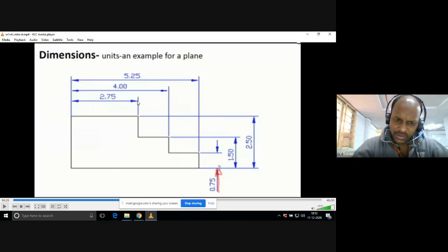Okay, you have to draw like this, just a bubble inside it, and you have to place this dimension line in between extension lines. One vertical line I am showing you here, and other vertical line I am showing you here. You need to keep the dimension line within these extension lines. These are known as extension lines. All are drawn with 2H pencil only, except the main drawing, which is drawn with the HB pencil.